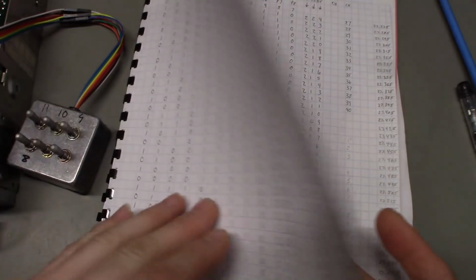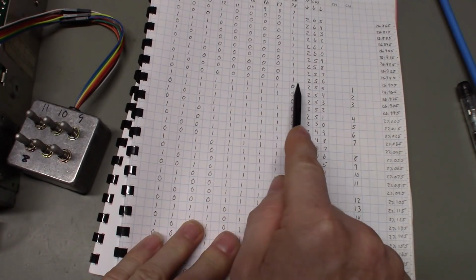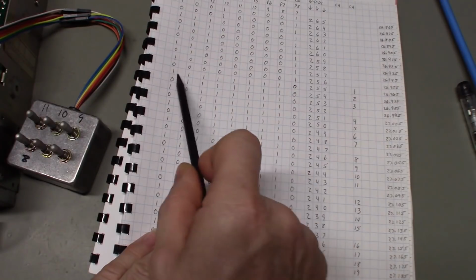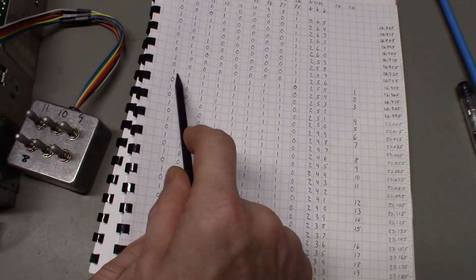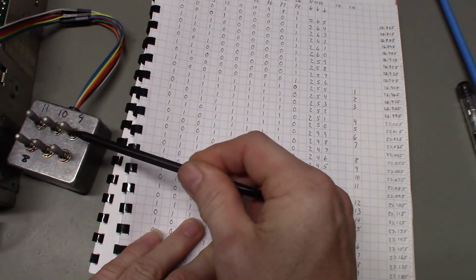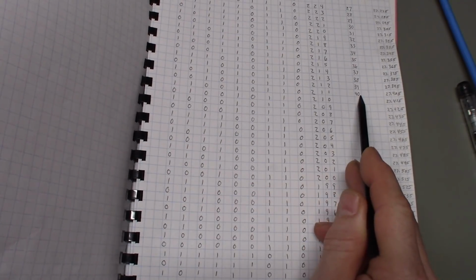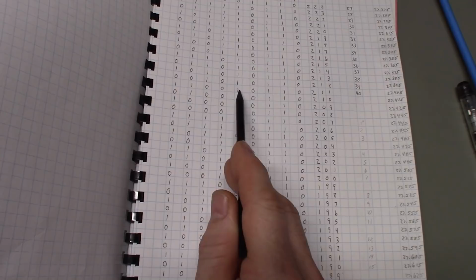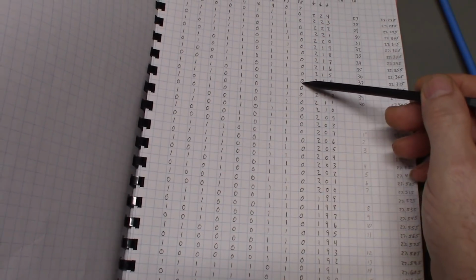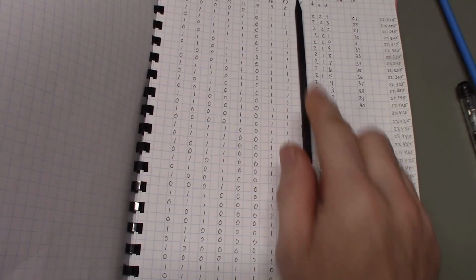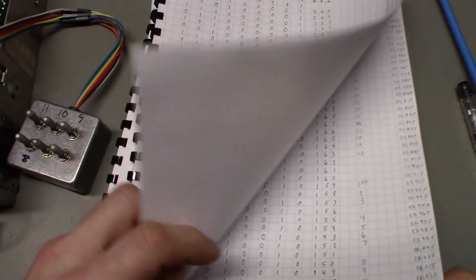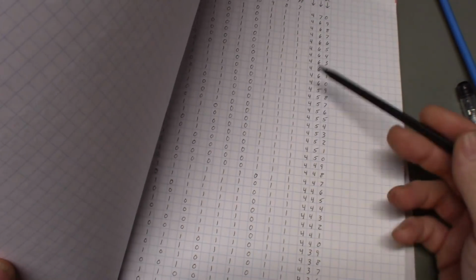So now if we look at what we're looking for when we want to add channels, remember channel 1, all ones and a 0. So we want to try and find somewhere where there's a lot of 1s, because the more 1s there are, the fewer pins we have to put toggle switches on. Here's the end of the CB band, channel 40, okay? That's 1100, 10, 110. Now this pin is never going to change state, so we really never have to worry about pin 7. By the time you would get to the point where it would change state, you would be so high, the radio's never going to cover it.